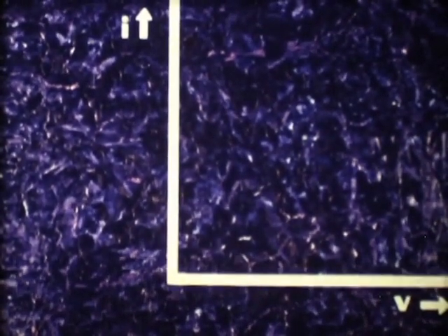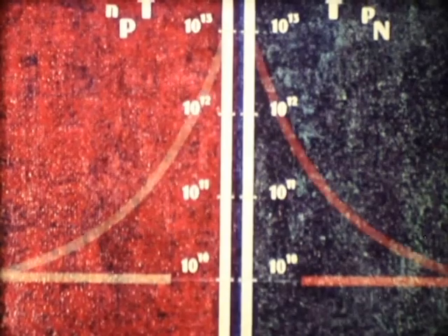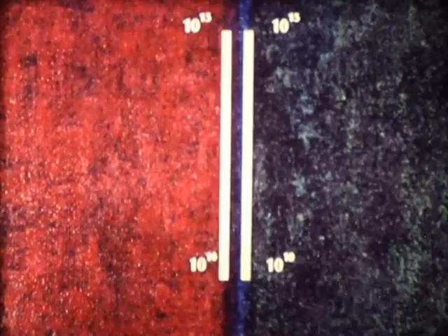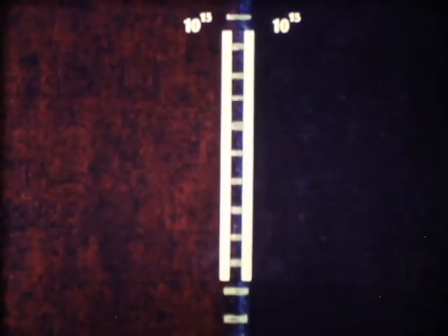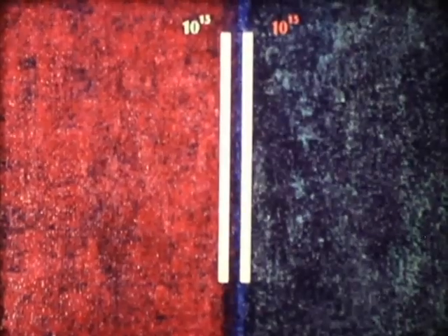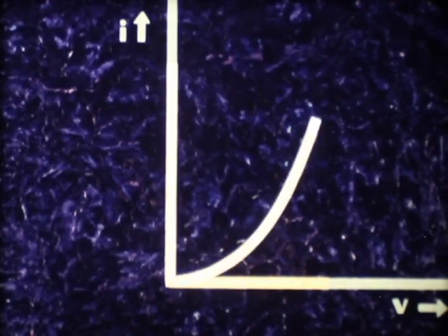If the forward voltage applied is 3 times greater than its original value, then the deviation shown on the logarithmic scale will also be 3 times greater, whereas the actual number of free electrons and holes flowing across the barrier will be about 100 times greater. Thus, the number of charge carriers increases exponentially. Therefore, the current voltage characteristic of the junction must also have an exponential shape.